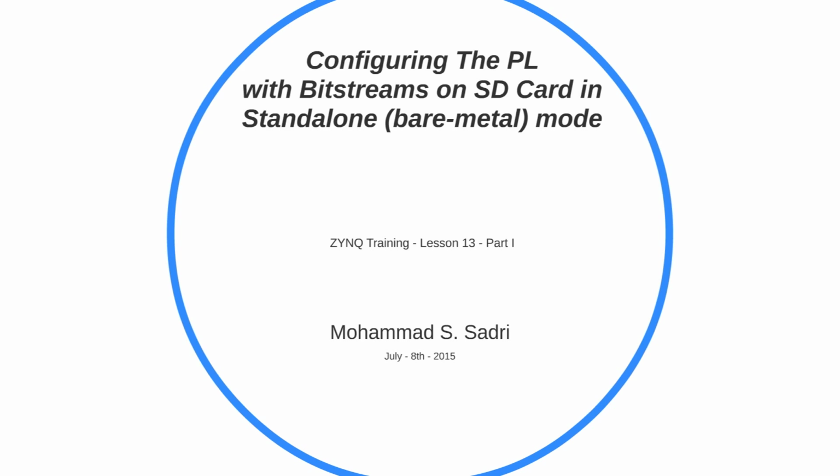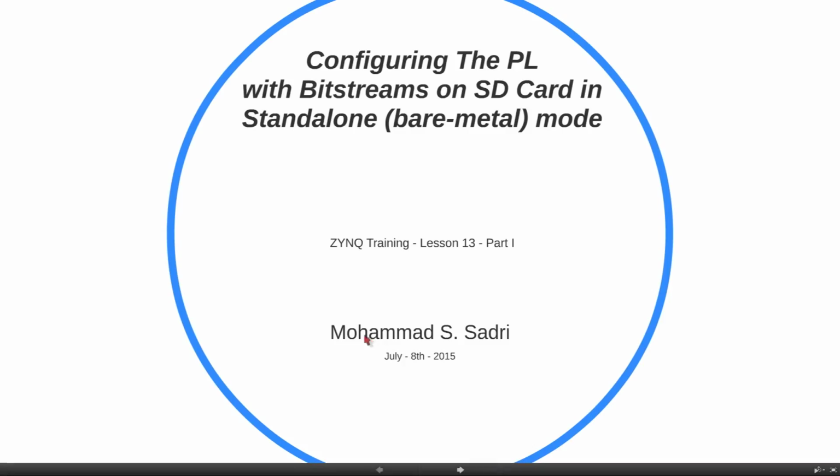As the name shows, the purpose in this video is to be able to read new bitstreams from the SD card and then reprogram the PL at each moment in time with the bitstreams stored on the SD card. And the whole thing we want to do in bare metal or standalone mode.